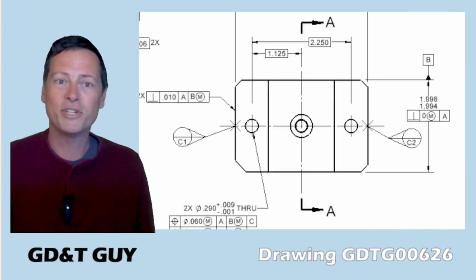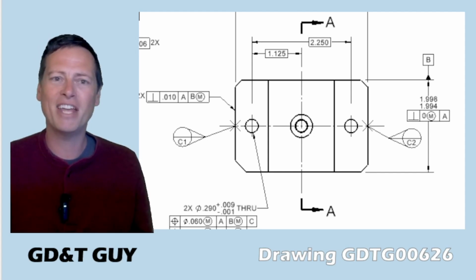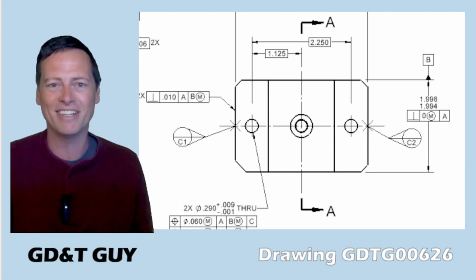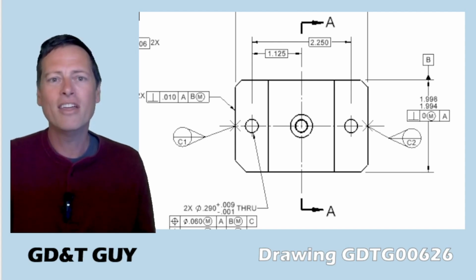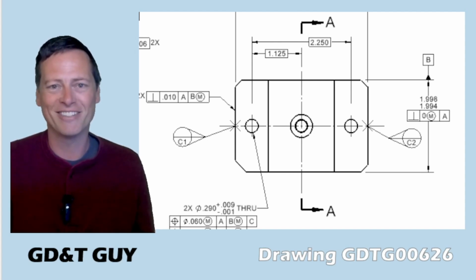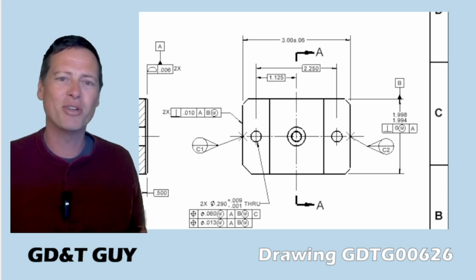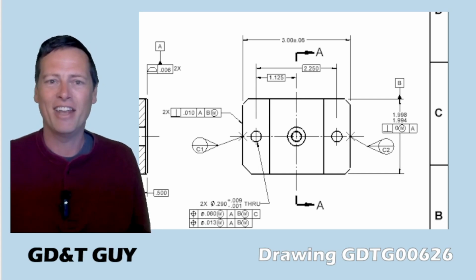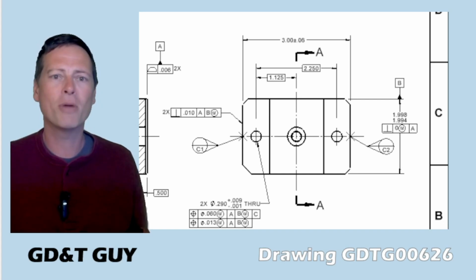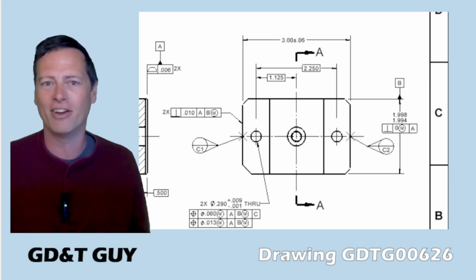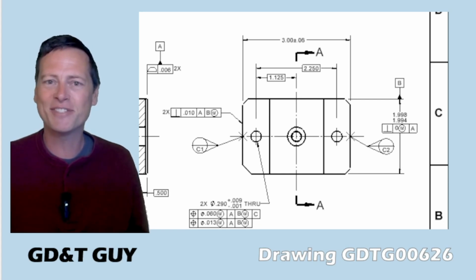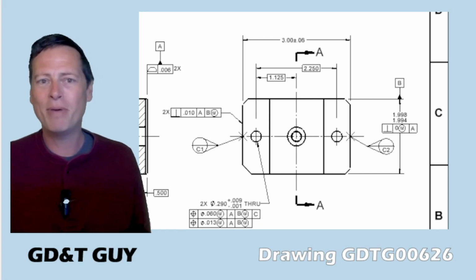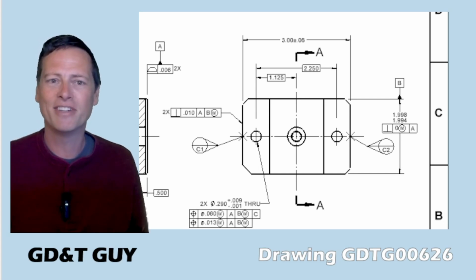I like that, and it also gives me some form control I didn't have before within the 10 thousandths perpendicularity limit, which is good because now I'm going with these datum targets to identify datum C. And because we're going to be referencing datum C as RMB, these have to be moving datum targets. So those are just some things to deal with my mini grievances. And it just makes this datum C feature more believable as a 1-DOF tertiary datum reference, right? I also like the idea of the inspector, if this is CMM, only having to pick up these little datum target areas and find the midpoint for datum C.